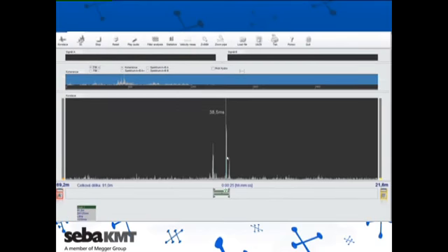The right peak corresponds to a leak distance of 21.8 meters from the yellow transmitter, which corresponds to the actual leak location within the section measured. The left peak points to the orange sensor, which indicates a possible leak outside the section measured in this direction.